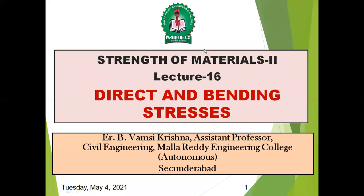Why? Because in practice, all beams will be subjected to lateral force. We should not call it direct force, we should call it lateral force, or vertical load, or you can also call it bending load. Understand? So due to lateral force, beams will undergo bending. Due to direct force, the same rectangular cross-sectional beam will undergo elongation or compression. So that is how individually we have studied direct stresses on different cross-sectional members, and bending stresses on different cross-sectional members like beams.